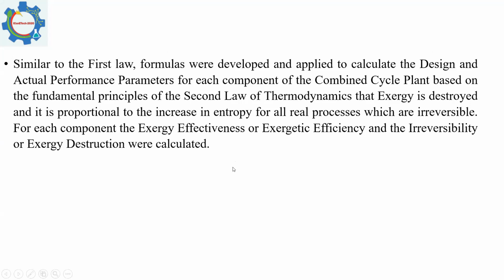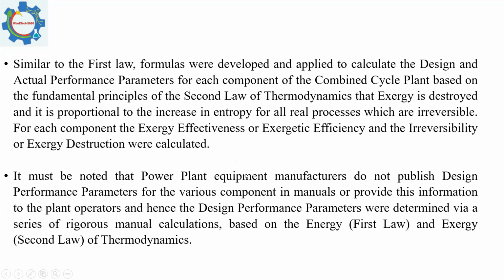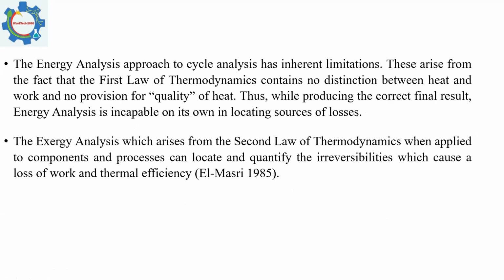Similarly, the first law, we did the same for the second law. In the case of the second law, we calculated the exergy effectiveness or exergetic efficiency, and the irreversibility or exergy destruction also calculated for each component. And so we were able now to compare the actual performance on the basis of the energy or first law analysis, and also on the basis of the second law analysis.